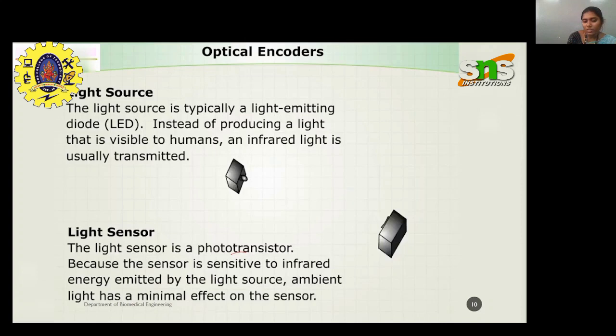Okay, in current generation, there is a photo current, so you can have it at the collector and also the emitter. When you measure the voltage drop across these two, you can get the output over here. That output is directly proportional to the amount of light incident on the base terminal of the transistor. So this is the generalized mechanism of a phototransistor.